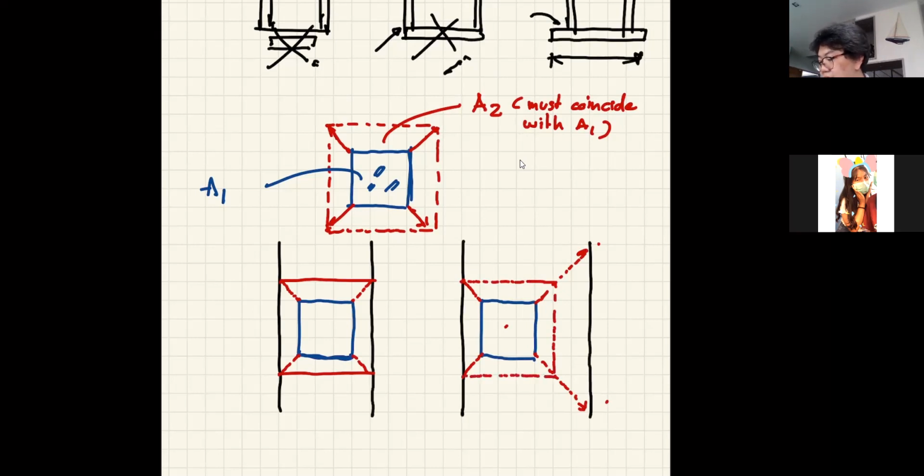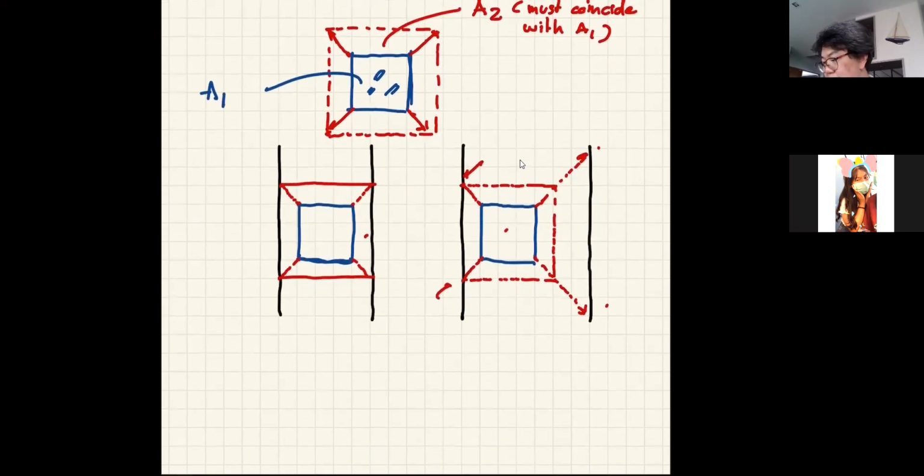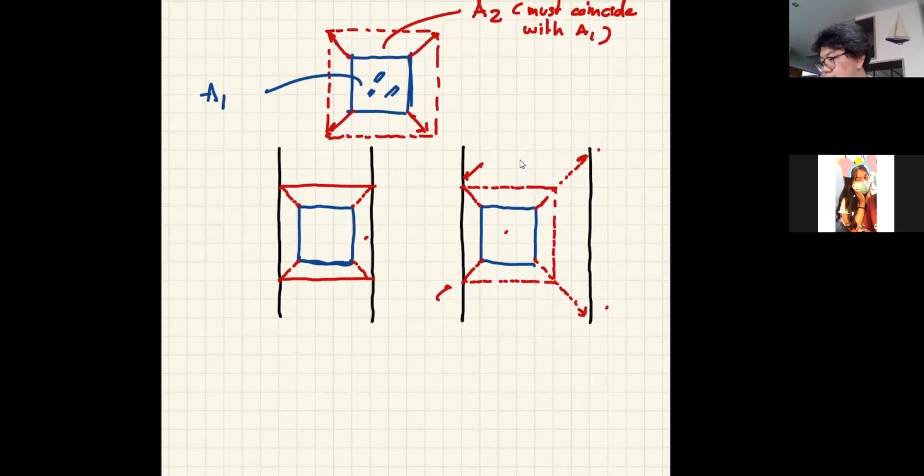And you see, in this case, the area anywhere beyond this is useless because we hit the boundary on the left, and because the distribution has to maintain the one-to-one ratio, which is rather conservative, but it's a model that they use and it works rather well. So that means your A2 here is pretty much the same as your A2 here, despite your plate sitting on bigger concrete. Okay, so let's say I give you one more.